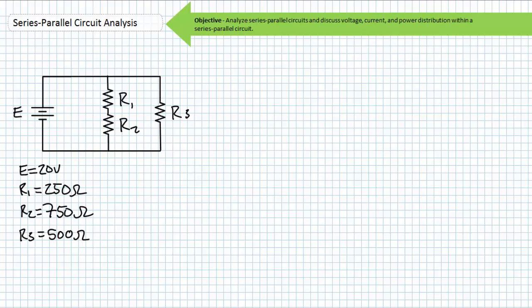First, before you enter a single number into your calculator, what is the relationship of IS, I1, I2, and I3? And what is the relationship of E, V1, V2, and V3? Meaning, are any of these values equivalent to one another, or do any of these values summate to other values? The point is, don't make yourself solve for things you don't have to. Current in a single path is the same. Voltage across paths in parallel is the same. For every rise there is a drop, and what goes in must come out.